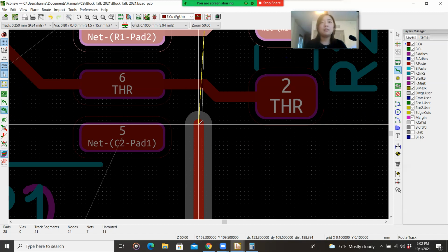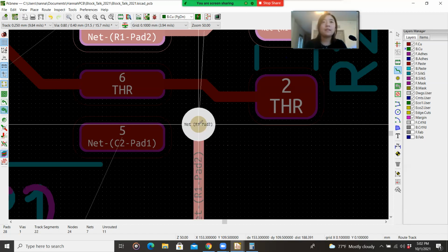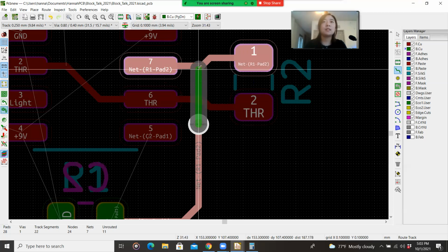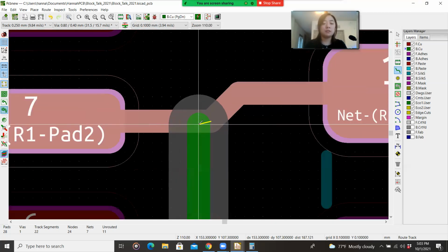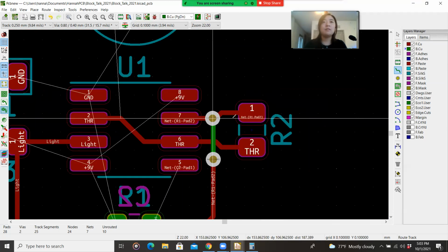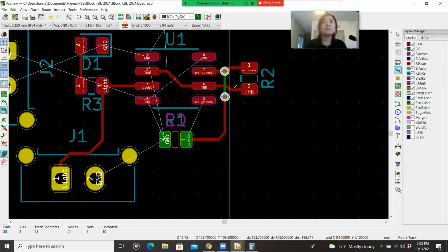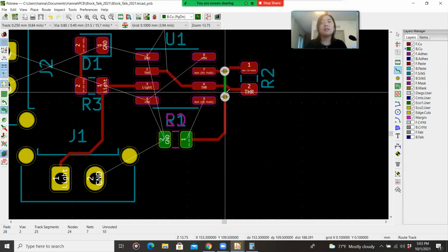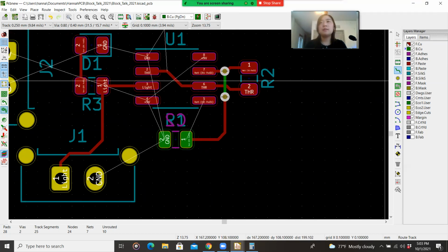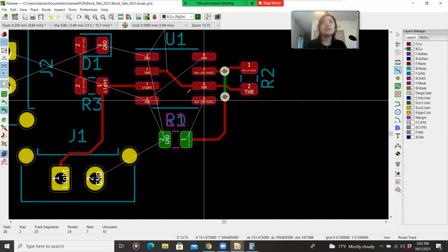And so how do we do that? If you press V here, then we lay out something that's known as a via. Then we keep going to the other side. And we can lay vias on other tracks. So we can just lay a via here and then connect it. So now we've connected it from the front side, and then we looped over to the back side. So now we have that. Notice that we can change which layer that we see first. Here, front side, back side, front side, back side. You can also change it here as well.